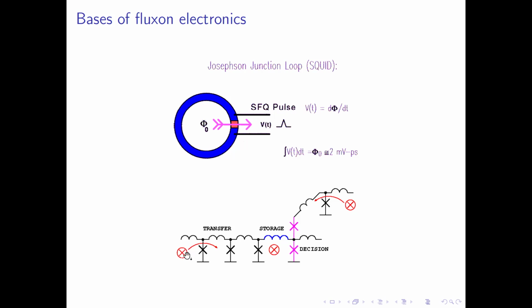And you can exercise this story if you have superconducting cables, like two superconducting cables, and there will be some Josephson junctions in between, and then you can force this magnetic field to move from one cell to another cell with proper voltage impulses, or current impulses. You can also use current as a modulating factor. So this is the so-called Josephson junction transmission line. Your magnetic flux can move from one to another. And the presence of one quantized vortex means logical bit one, and its absence a logical zero.